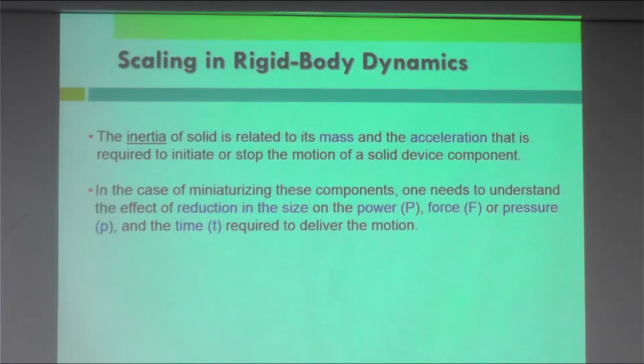The inertia of a solid is related to its mass, and the acceleration that is required to initiate or stop the motion of a solid device component. In the case of miniaturizing this component, one needs to understand the effect of reduction in size on the power, force or pressure, and time required to deliver the motion. So these are all the scaling laws that need to be looked at or calculated prior to the design of the materials or the device.